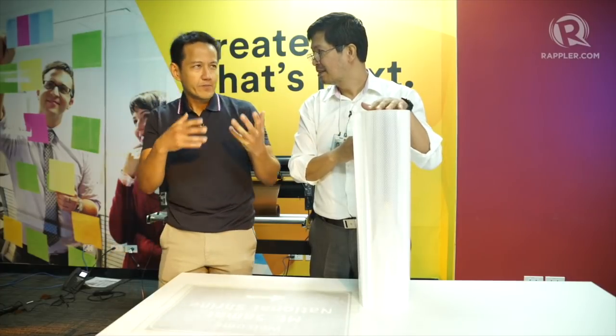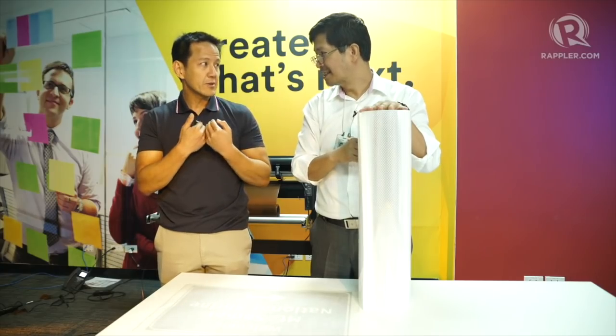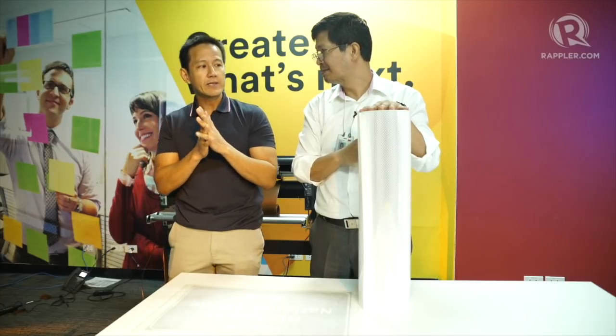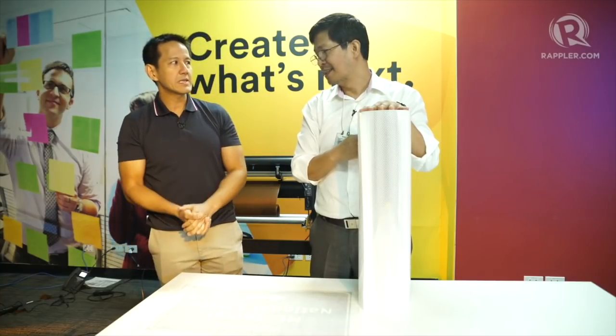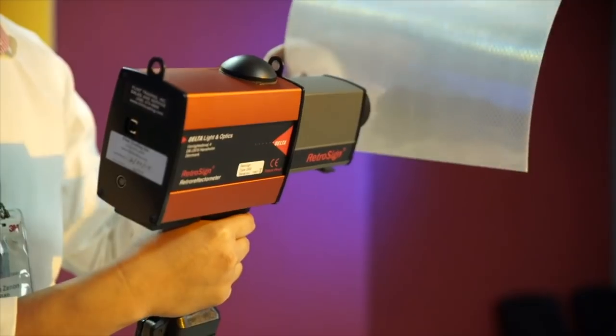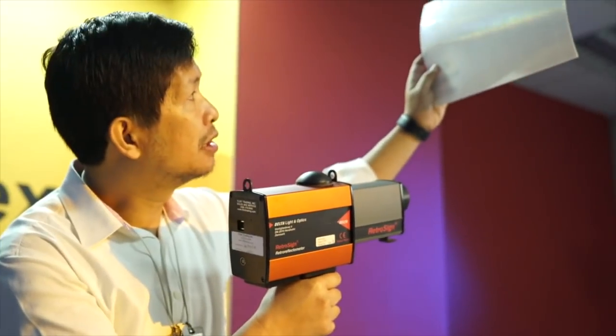Being a bit of a nerd, how much of that light is reflected? If you have 100 coming in, how much comes back out? About 50 to 70% of the light that shines on it comes back to the viewer. Not bad. And that's enough for the viewer to be able to see these. Yes. And for the standards, we have a specification for how much light has to go back, and we use an instrument called a retroreflectometer.